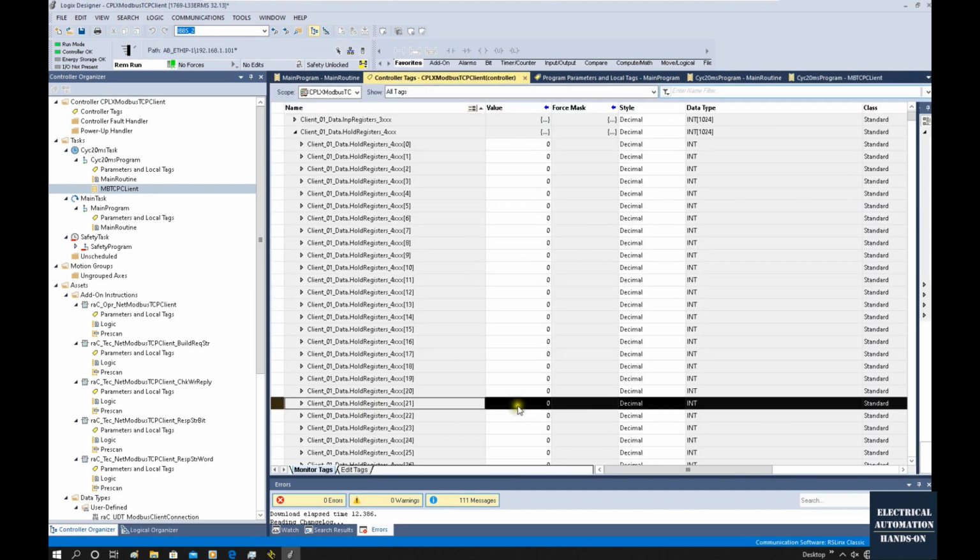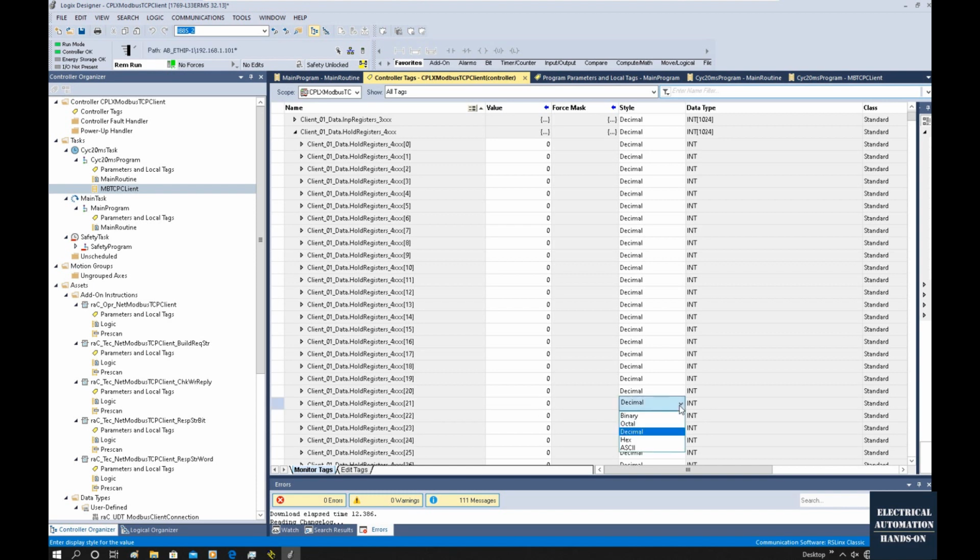Here we can prepare the data. To test the data, I recommend we start by using hex values, for example ABCD. Using hex, we can clearly see if the low byte and the high byte are sent correctly. Sometimes the high byte and low byte will be reversed.